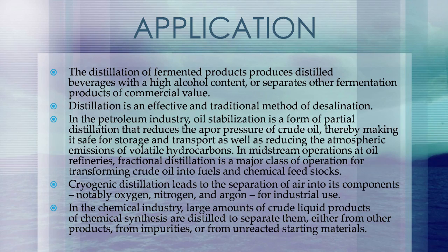In batch distillation, the composition of the source material, the vapors of the distilling compounds, and the distillate change during the distillation. In batch distillation, a still is charged with a batch of feed mixture, which is then separated into its component fractions, which are collected sequentially from most volatile to less volatile, with the bottom remaining least or non-volatile fraction removed at the end. The still can then be recharged and the process repeated.